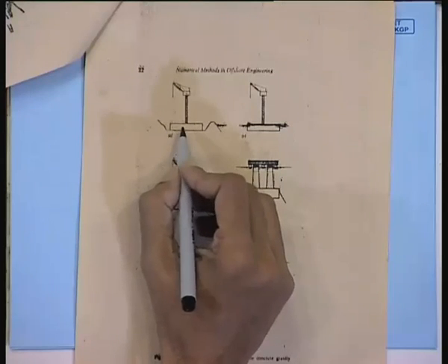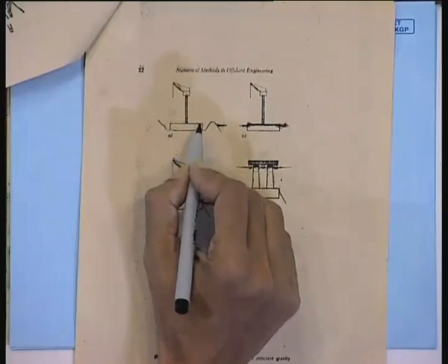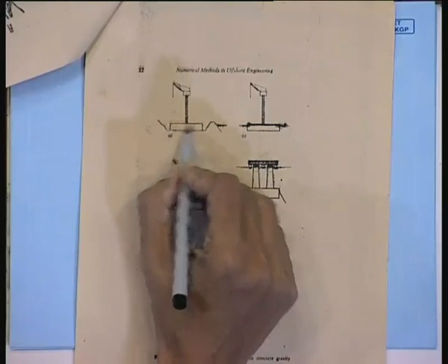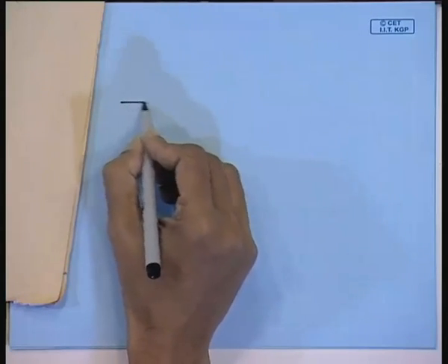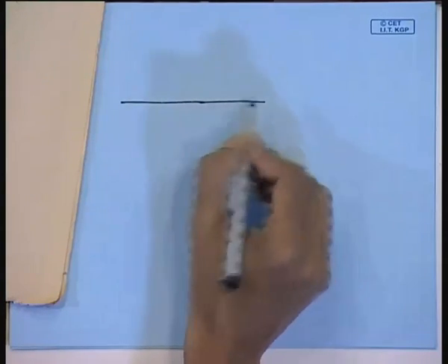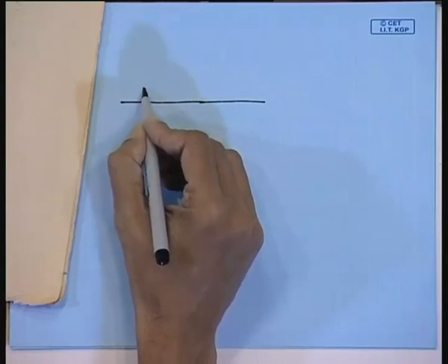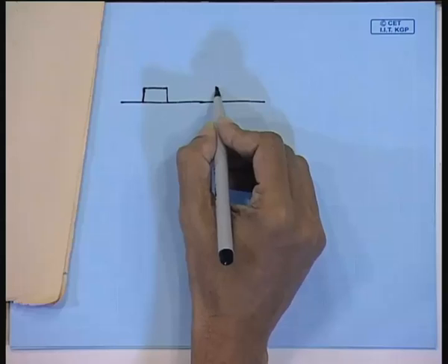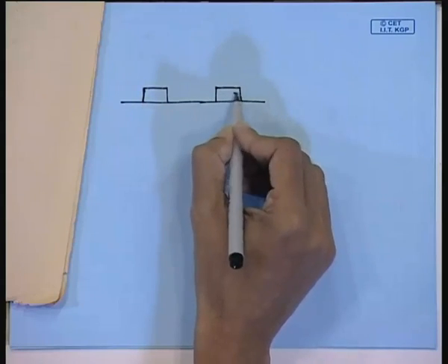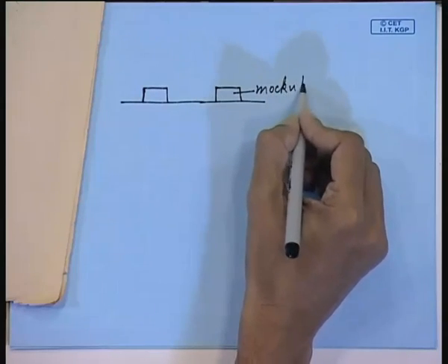So, the bottom part consists of only the base slab along with part of the caisson. You never build the whole caisson in the shipyard. So, what is done in the shipyard construction is, say this is the bed of the dock, and you build some mock-up columns. These are called mock-ups. In your shipyard training, I don't know whether you have seen this kind of mock-ups. These are called mock-up columns.